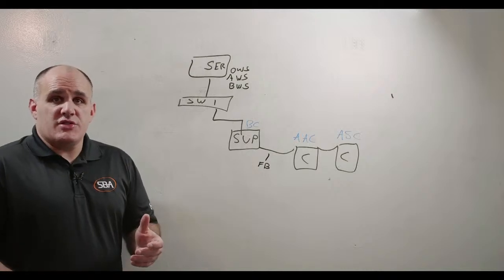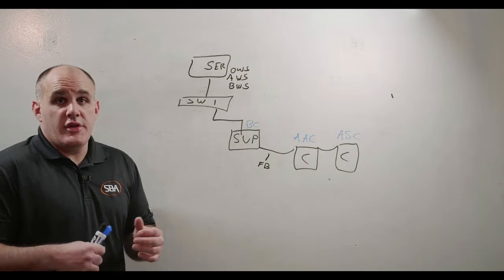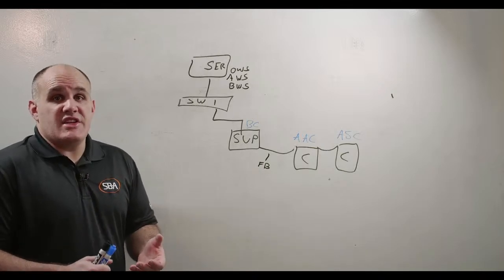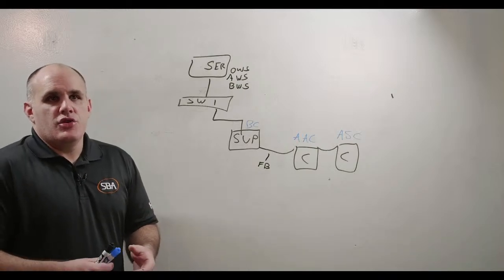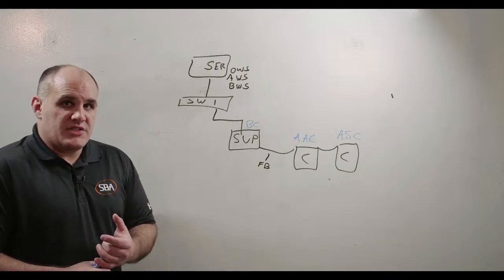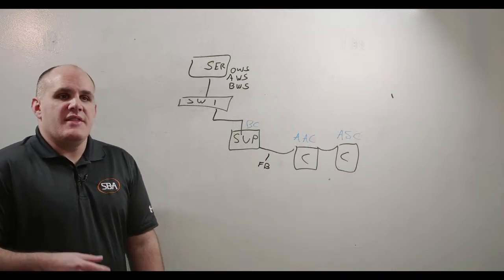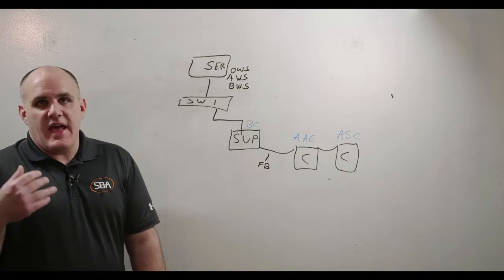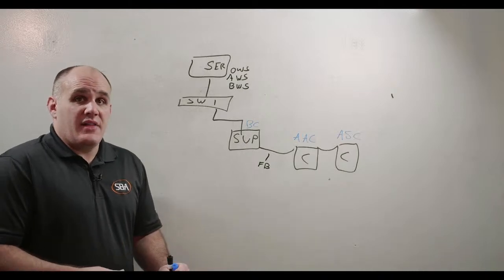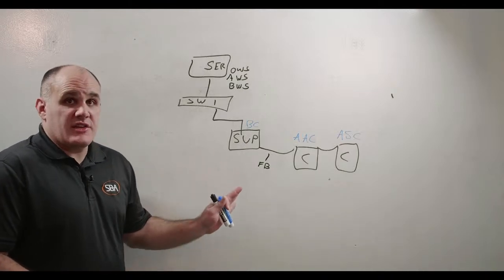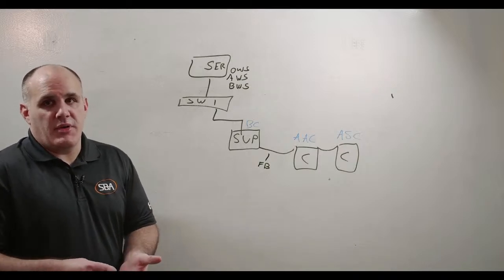So how do you do this? Well, you would go to your mechanical plans. You would look at your equipment schedule. You would do a takeoff. You would understand which terminal units you have, which air handlers you have, which hydronic plants you have. You would then understand what I/O requirements you have. So I like to build out my I/O bill of materials first. Then once I have a complete bill of materials and that list of I/O, from there I like to pick my architecture type and pick my controllers. Typically, I'll pick my controllers and then I'll pick my architecture type.